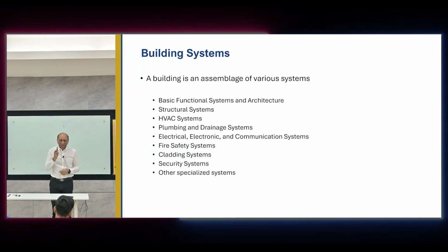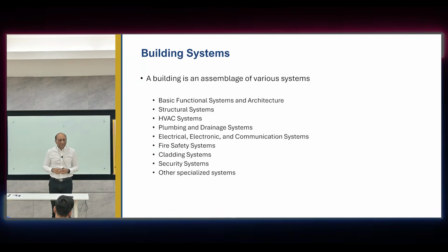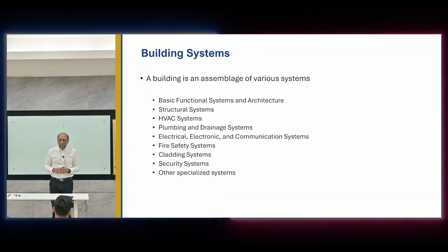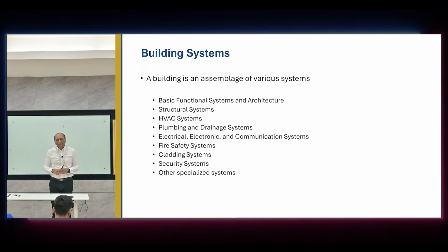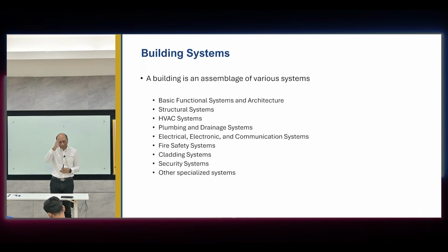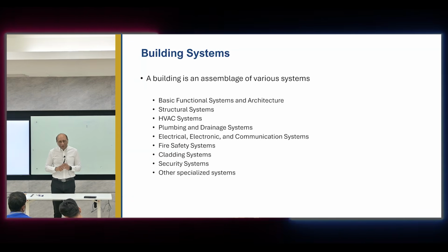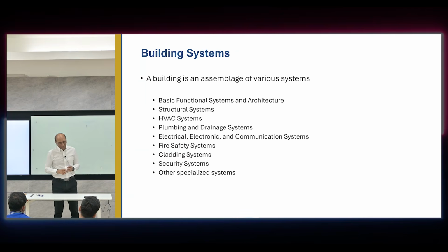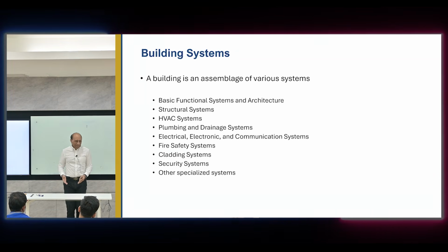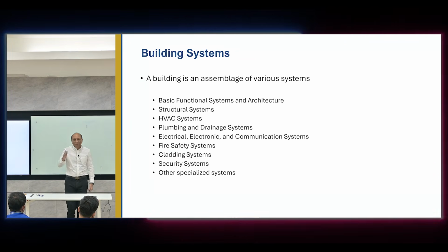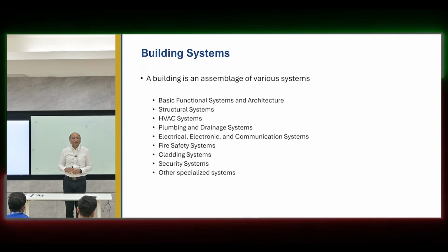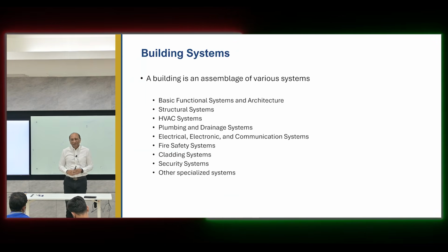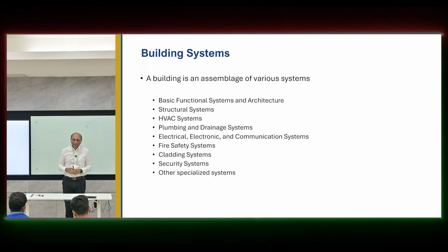Let's say it's a 100-story building. How much do you think it will deform in a typical earthquake? A 300-meter building. How much do you think it will move at the top? In a strong earthquake, a building can move up to 6 meters. 6 meters. If I'm here, 6 meters is the whole room. So a tall building is expected to, within safe limits, without falling down, without breaking, have the ability to move around 5 to 6 meters.